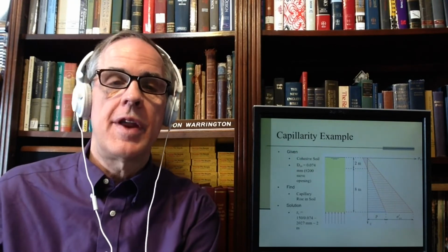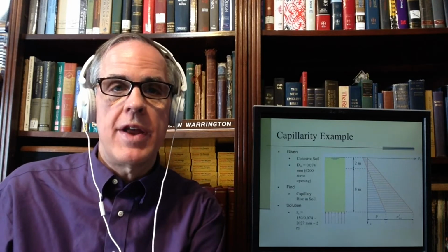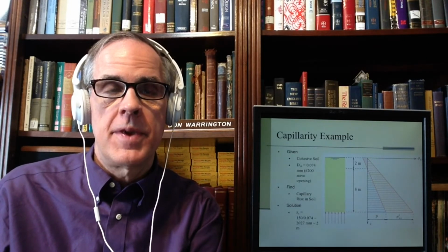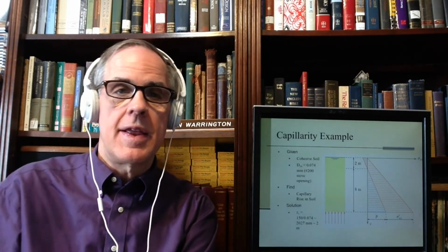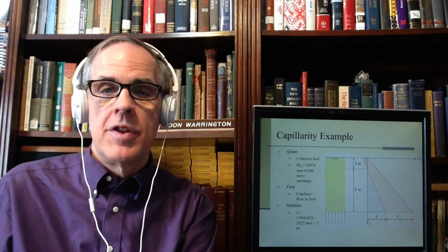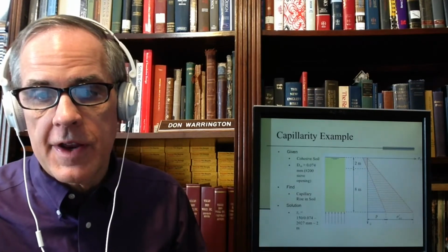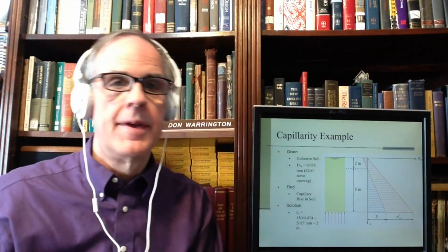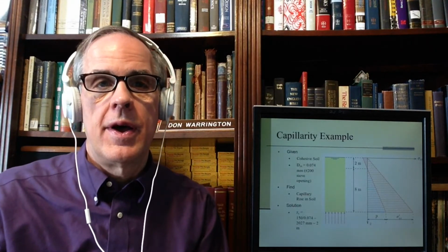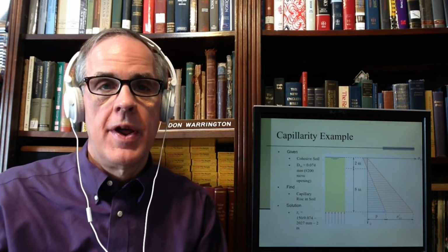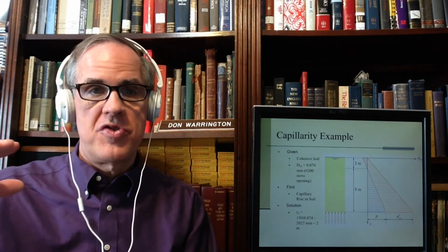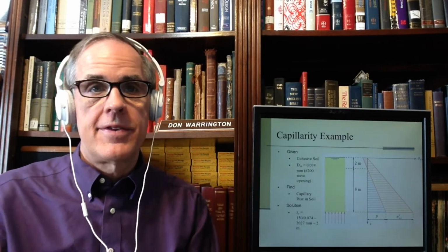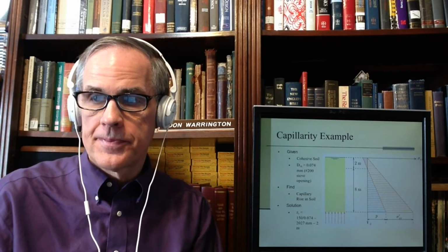I say that the water table is the point at which the pore water pressure is 0. Because above that, if you have capillary rise, the pore water pressures, as you see here, are negative. The soils are consistently saturated below it and sometimes saturated above it.